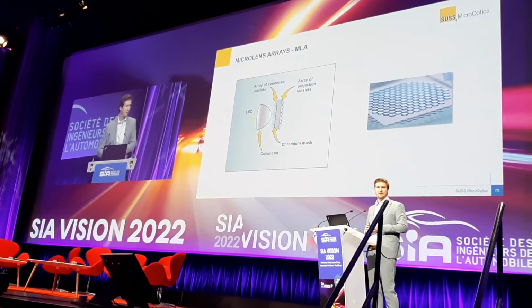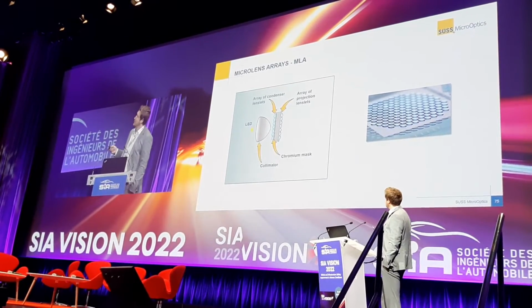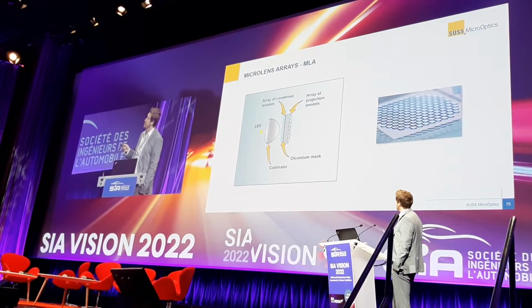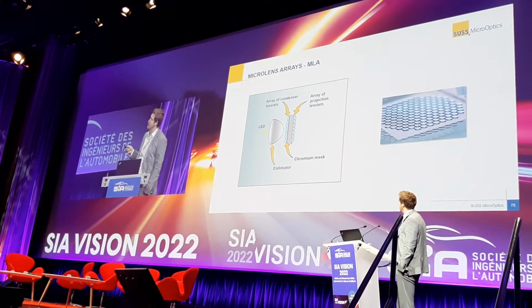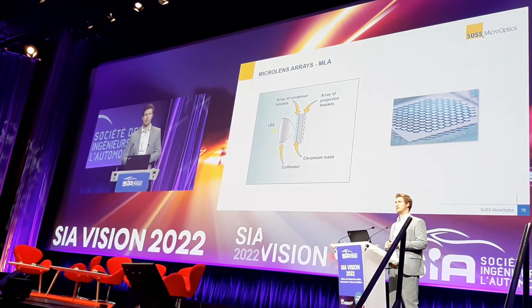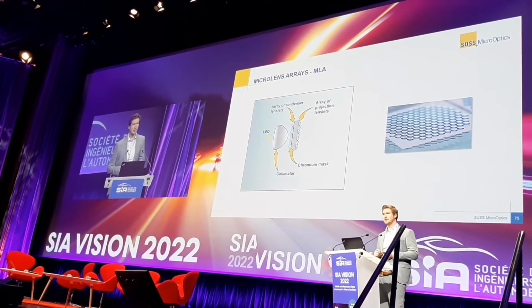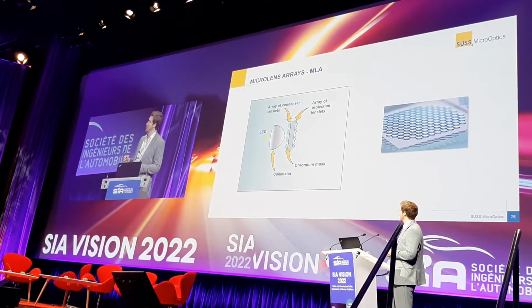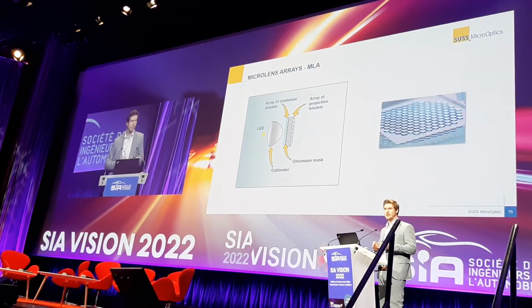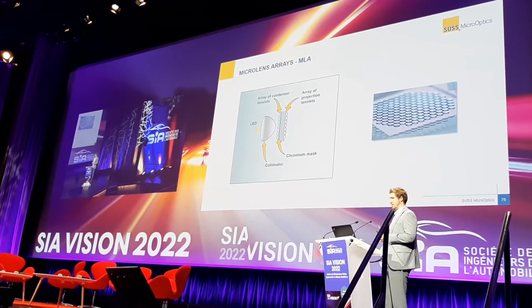For those that are not that familiar with the micro-optical system, usually we have an LED and collimation optics, and this is the part we manufacture. So there are a lot of micro lenses. In this case, the overall chip is roughly 1 centimeter by 1 centimeter, and the single lens is 0.8 millimeters. That's the dimensions where most of the micro-optical products are located. They can be different, they can be varied. I will come to this later when I have the production slides.